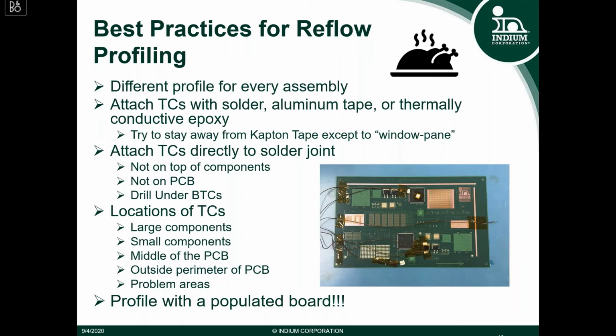Kapton tape is not a good method for attaching the thermocouples to the board, because Kapton is actually an insulator. It will affect your results and not give you an accurate temperature reading if you cover the tip of the thermocouple with Kapton tape. What I do use the Kapton tape for is to secure the wires of the thermocouples down to the board so that they don't get hung up in the oven.